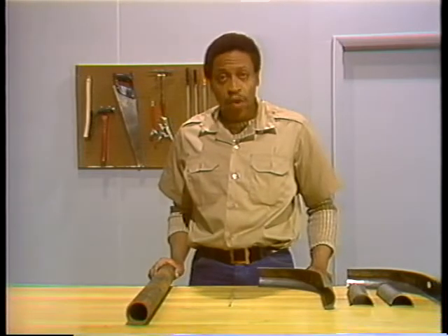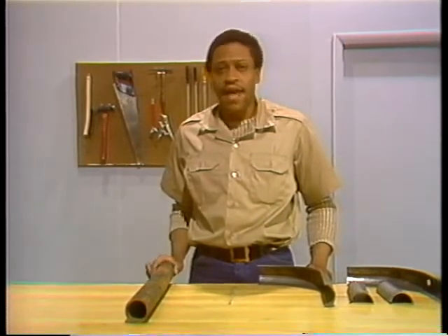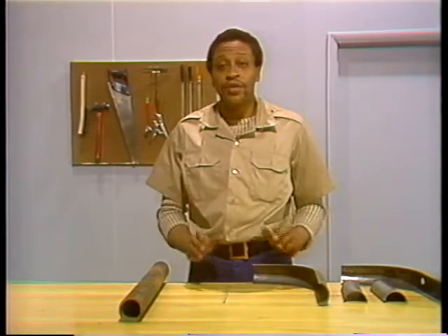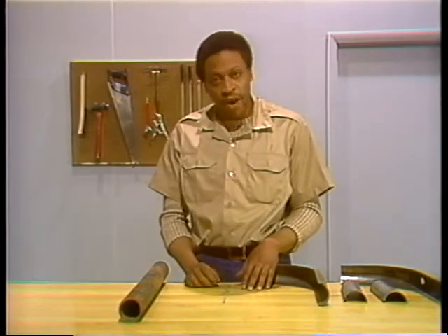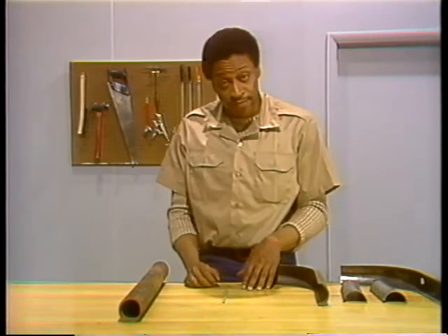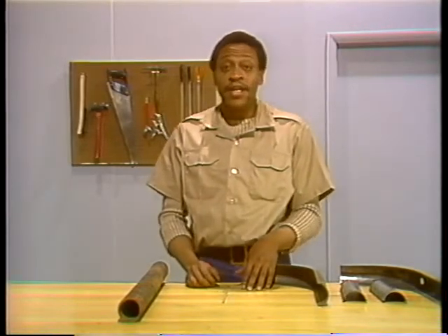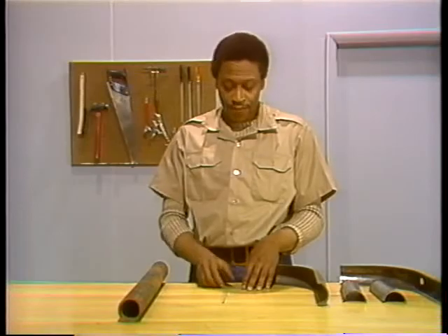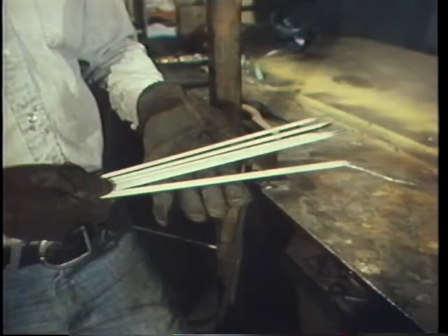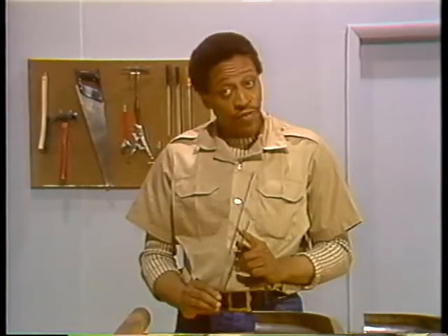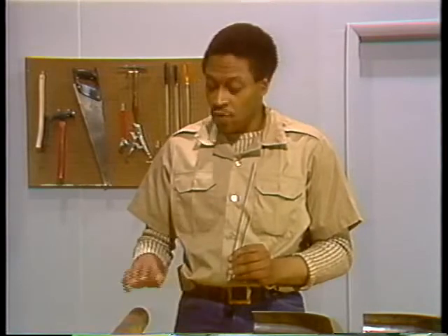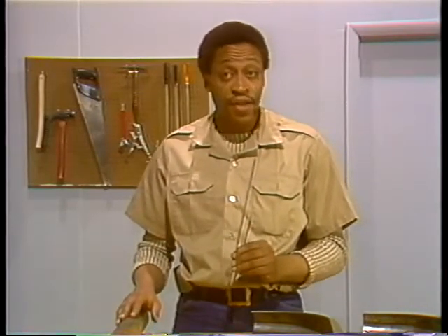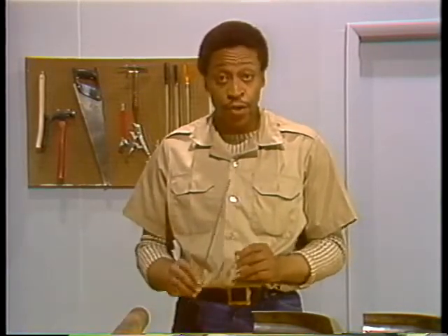Once it's been determined that a tube needs cladding, the first thing to do is to read through the cladding procedure. If a written procedure doesn't exist, talk the process over with an experienced welder. The next thing to do is to get the materials and tools together. The only material that is needed for a clad repair is weld rod. It's very important that the right weld rod is used. The rod metal must be compatible with the tube metal. If it isn't, the clad patch could eventually damage the tube.